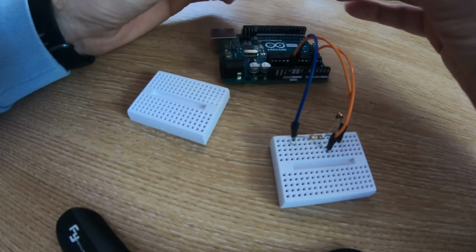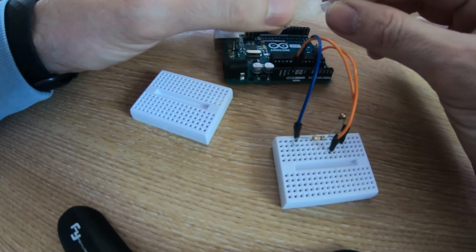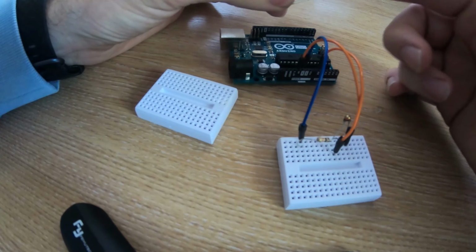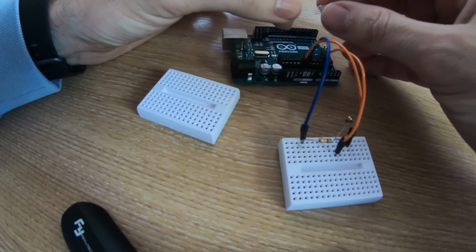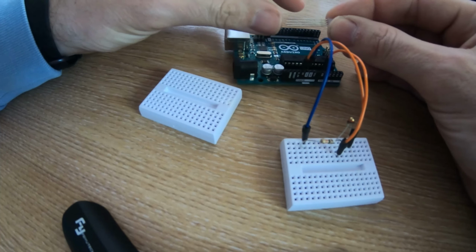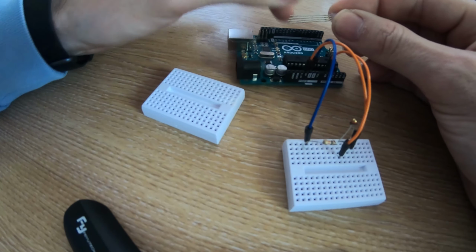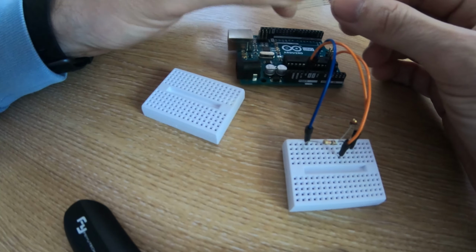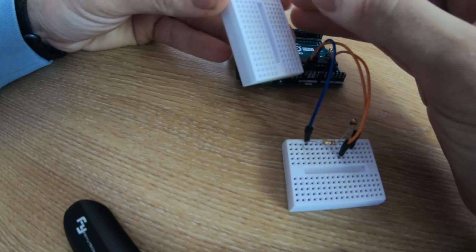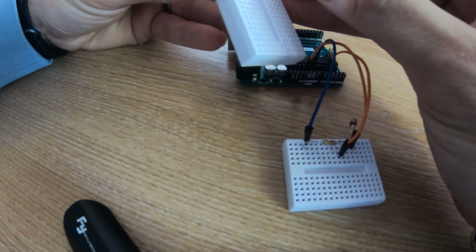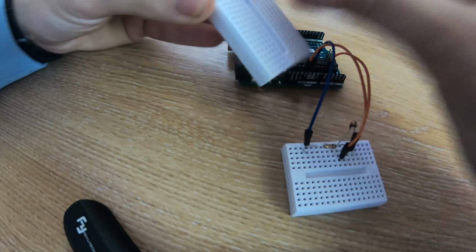Our process will be our program, and for our output we're going to use one of these, a Tricolor LED. Now, Tricolor LEDs have red, blue, green. There's a variety of different types, but they have 4 legs coming out of it. The long leg is the negative, and the other 2 legs, if you put positive power to those, it changes the colour. So we're going to stick that into our breadboard, and these are never easy to get into a breadboard because there's so many legs on them.